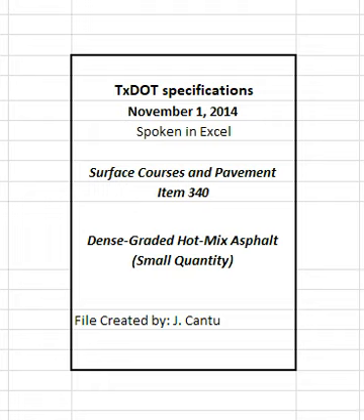4.6.3 Laydown operations. 4.6.3.1 Windrow operations. Operate windrow pickup equipment so that when hot mix is placed in windrows, substantially all the mixture deposited on the roadbed is picked up and loaded into the paver.